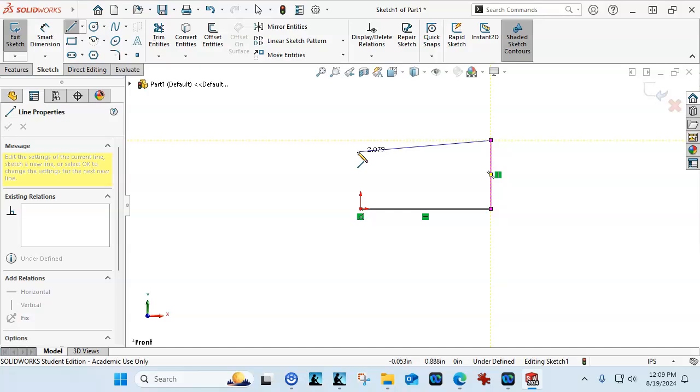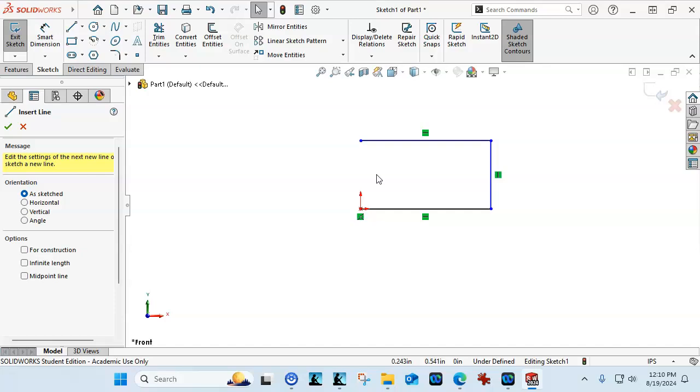All right, so yellow inference lines are showing me the horizontal and verticals related to what I drew last. If this was a circle, it might show me the tangencies, and when I snap to it, or it makes that little jump, then it goes to blue, and I will also get an inference line that tells me I am vertical. So I'm going to go ahead and go into the command by double clicking. Hey, it worked that time. So I want to go back into the line and go to a click and drag.